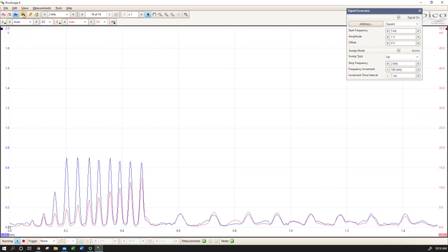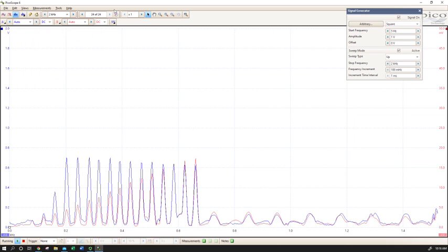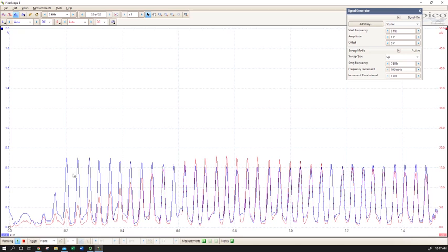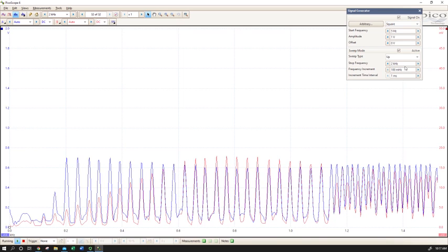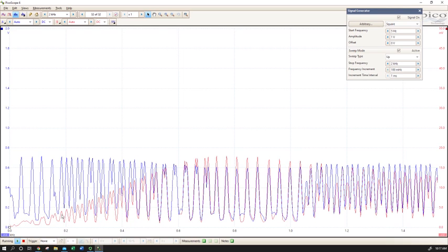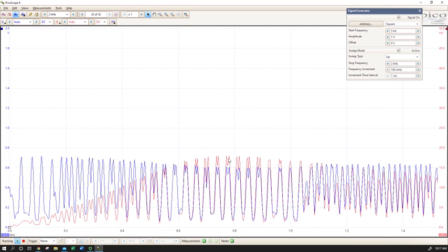The first thing I'm going to check is to make sure I'm on peak hold. As you can see, it looks like I'm collecting a bunch of peaks, and rather than having a line go across my display, what I'm actually collecting is a 100 millihertz window. And I'm collecting a voltage signal over that window, averaging it according to the Blackman-Harris model, and then displaying the top. So you can see we're only displaying the top number, and we are sweeping up.